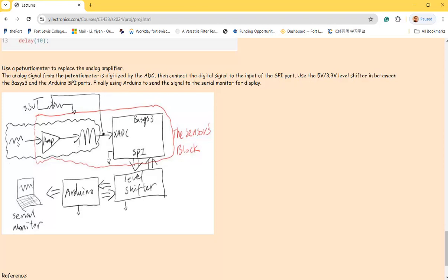And then use the middle voltage. For this example, it should be 2.5 divided by 2, so it's going to be 1.25 volts. And you need to amplify the signal only, not the offset. The signal only, so it's swinging around 1.25 volts.